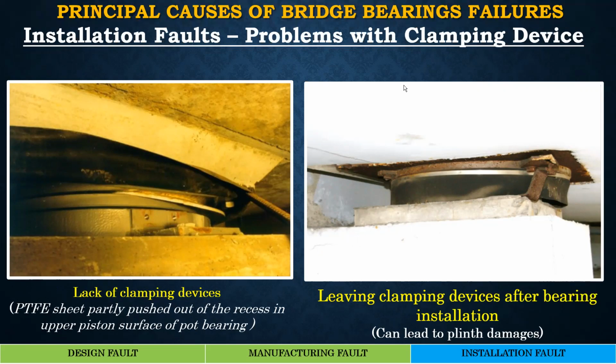The other extreme is leaving the clamping devices after bearing installation, which can lead to damages at many parts in the plinth. And I have personally visited many existing bridges after 5, 6, 7, 10 years of its construction. And to my surprise, I have seen in many cases that the clamping device were still there, and nobody has removed the clamping device. This should have been removed just immediately after construction, before putting the bridge on service.